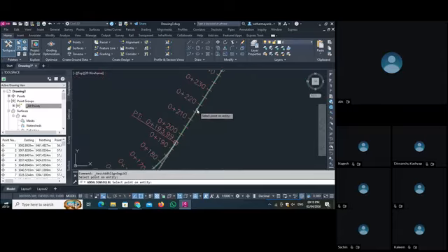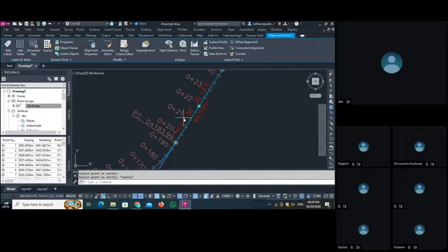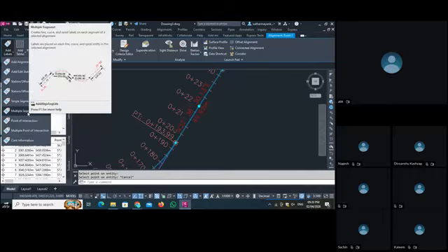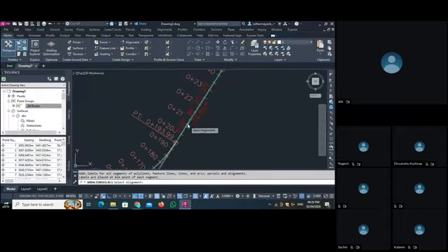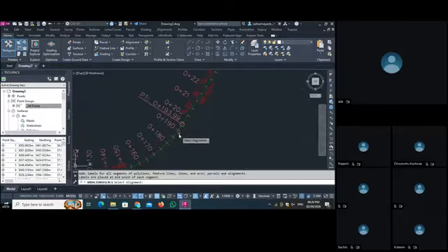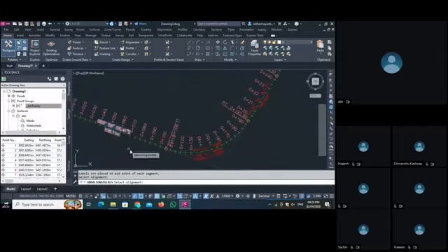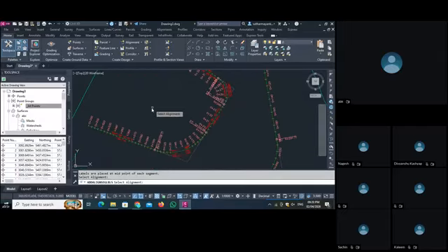If I select this here, it will give a single segment like our northing point, easting point, and the elevation point. So again, I click on the alignment. I select the alignment. I go to add label. If I want to select the multi segment, with the help of this multi segment, I can again and again click anywhere. If I select the multi segment, on every part they provide a segment.